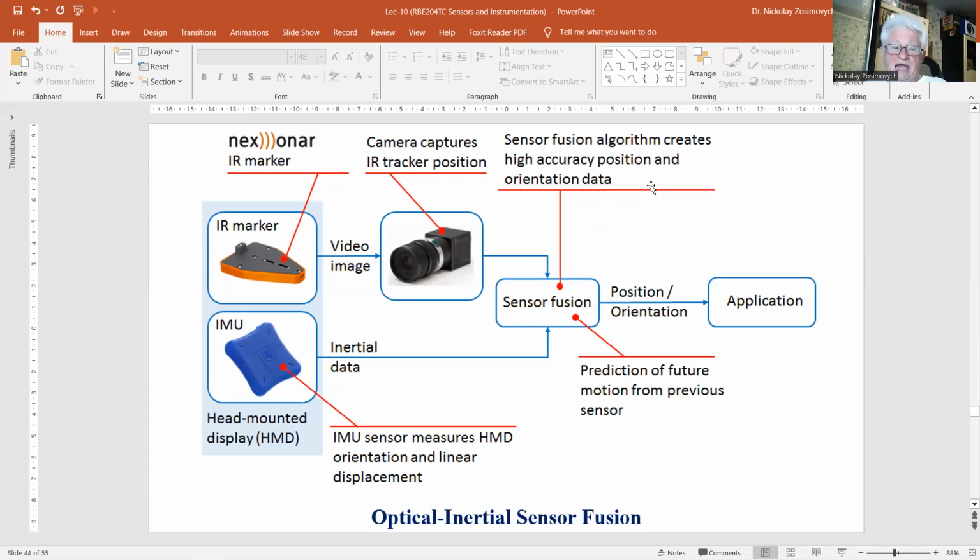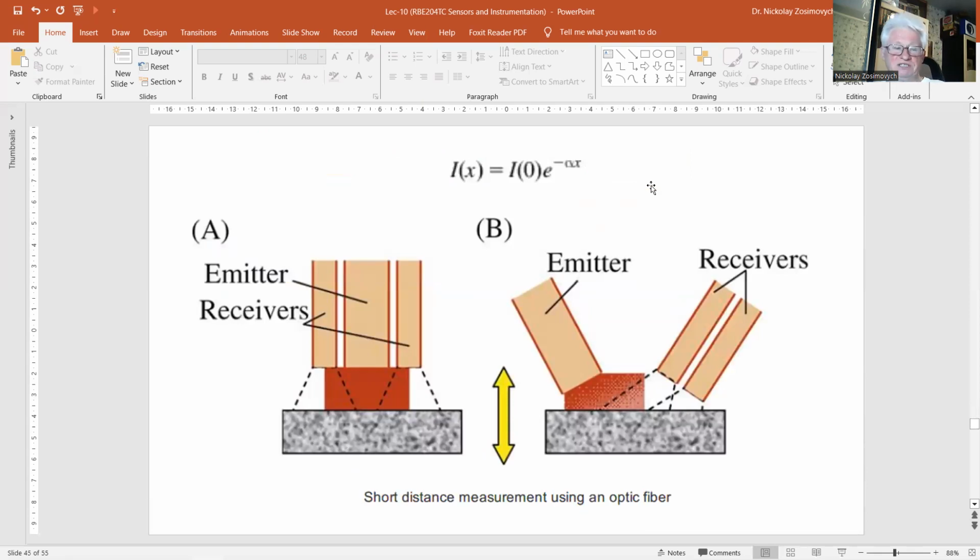This deformation can be measured in various ways, for instance, by optical means. However, the displacement is generally very small, and proper measurement requires a sensor with high resolution in terms of displacement. Configurations with optical fibers in reflection mode, like in this figure, are suitable candidates for this task.